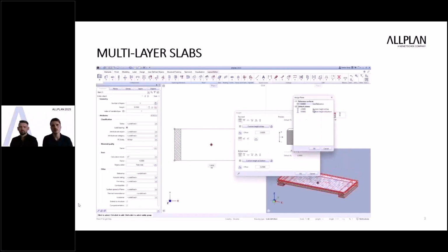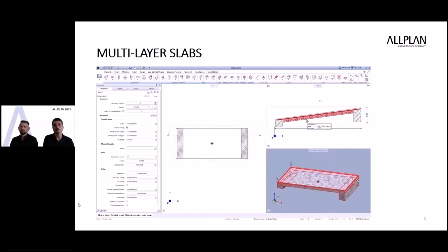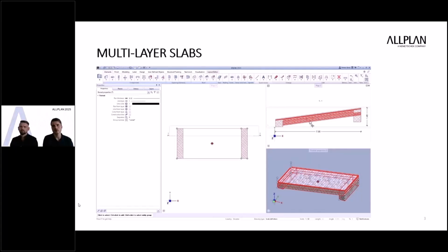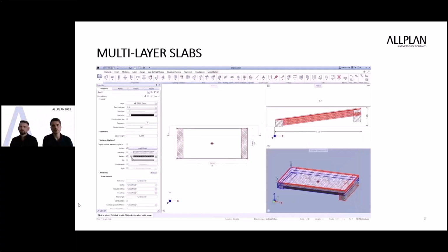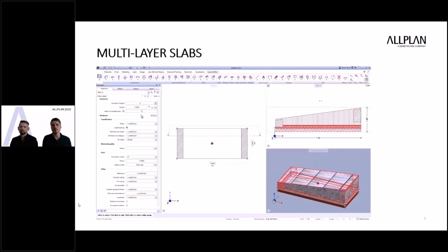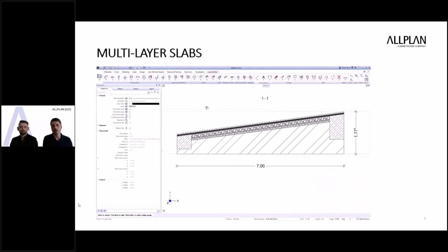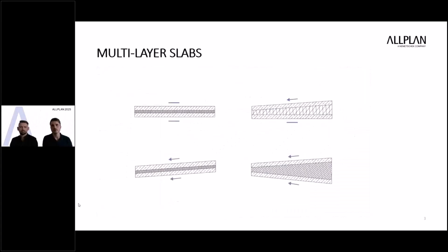By switching to the overall entire slab object in the property palette, you control general height settings of the top and bottom edge of the composite slab. That means all necessary settings are available straight in the property palette for faster workflows. Slope layers or a layer with non-consistent thicknesses are no problem with this new improvement.